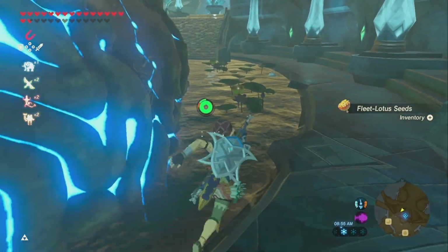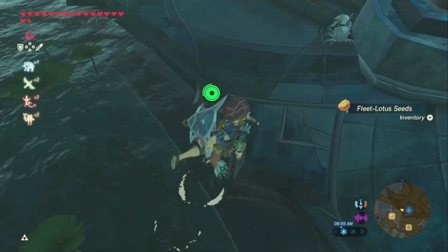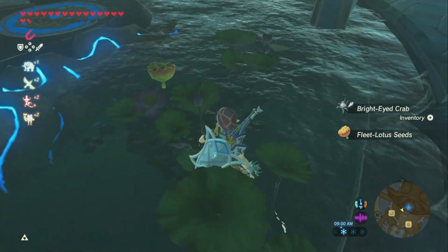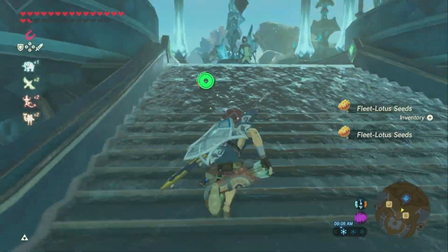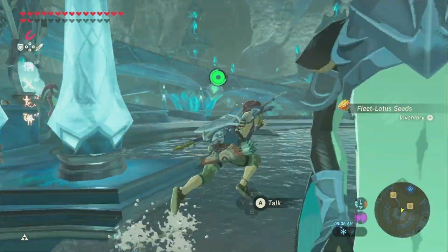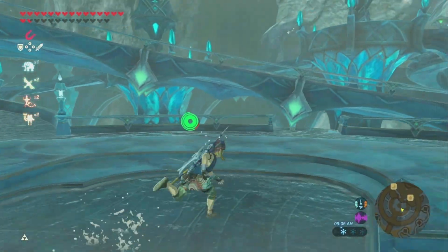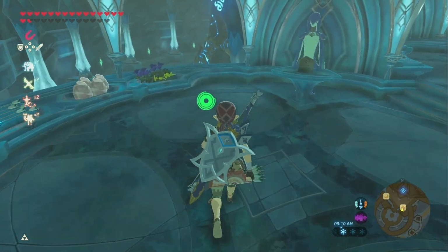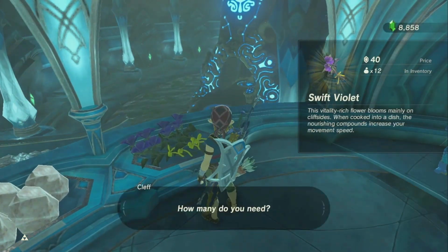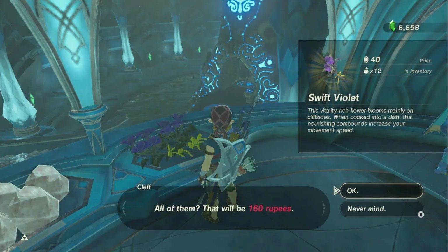Oof. Venting issues. The vents on power vented water heaters are typically smaller diameter than conventional water heaters. There are also different materials, PVC or ABS, that do not require any combustible clearances. ABS venting is not permitted in some jurisdictions.